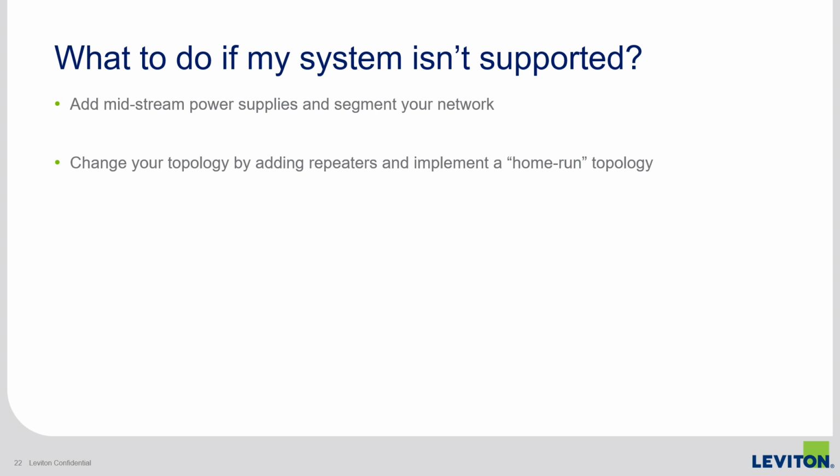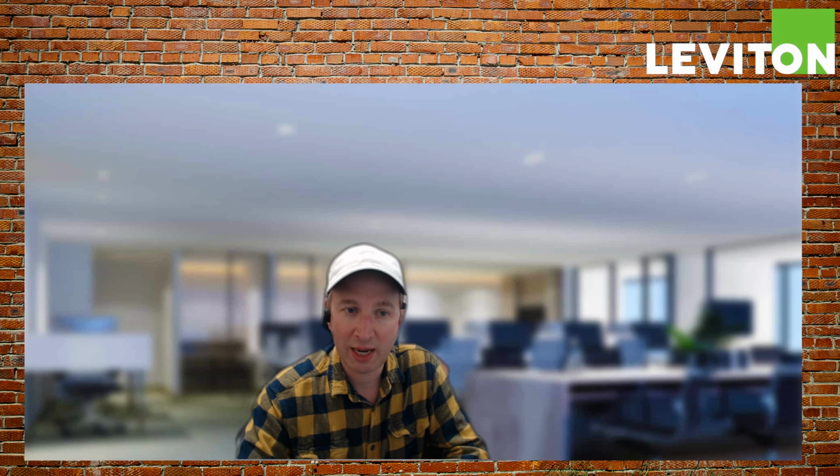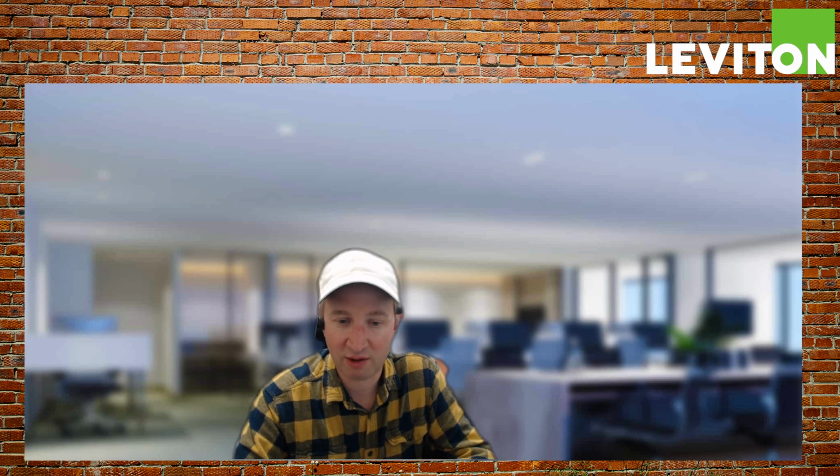So a lot that we kind of ran you through there, but basically I just wanted to talk to you about some basic power and data considerations for LumaCAN networks, as well as how to use the Alfred tool to make sure that you have enough power and make sure your power supplies are big enough on the network.